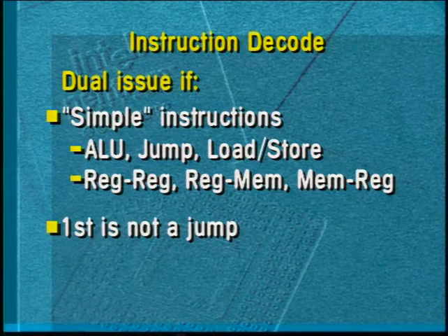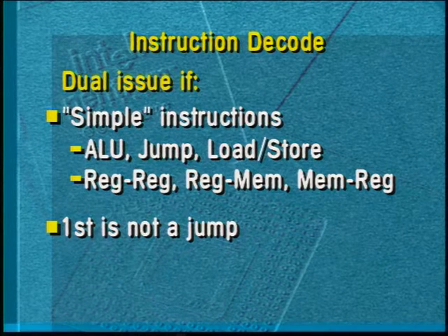By issuing only a subset of the instructions in parallel, we're able to handle resource dependencies. For example, there's only a single shifter in the U pipe, so all of the shift instructions are issued to the U pipe. Control dependencies occur when the result of one instruction determines whether another instruction will be executed. We handle these by checking whether the first instruction is a jump instruction.